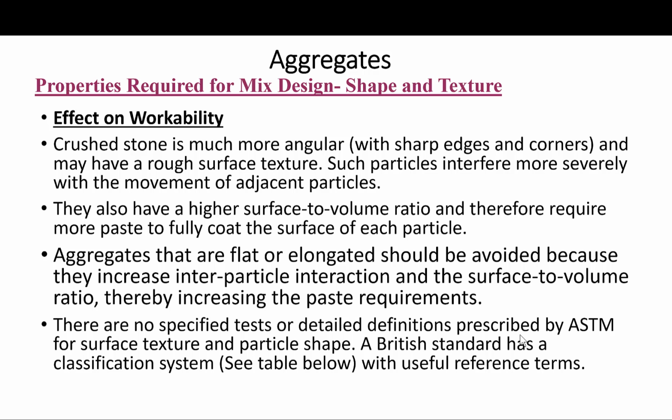So the surface texture of the aggregate is also important for workability, since a rough surface requires more lubrication for movement, which is more paste. The crushed stone has a rougher surface than natural sand and gravel because the surface has not been worn smooth by the effects of the water and the weather. Okay.